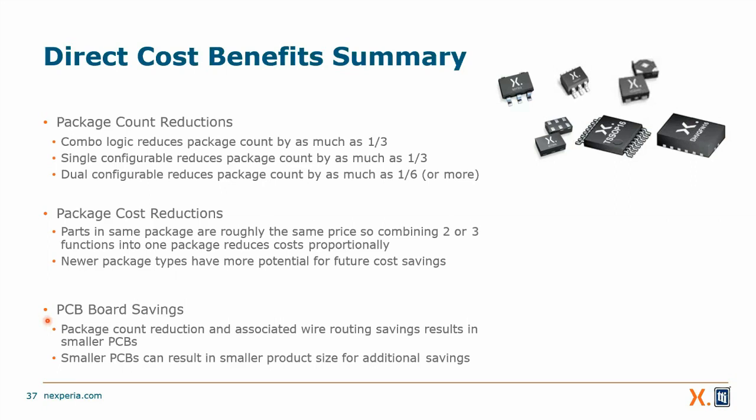And then finally, there's the PCB board saving space. If I have a lot of logic gates, and we may have from 5, 6, a dozen of them in a very small package, being able to reduce my PCB by getting rid of the number of devices, by making my board physically smaller, I'm saving on raw PCB cost. It costs so many pennies per square inch. I'm reducing the number of square inches I need for my board, and I'm saving there directly.